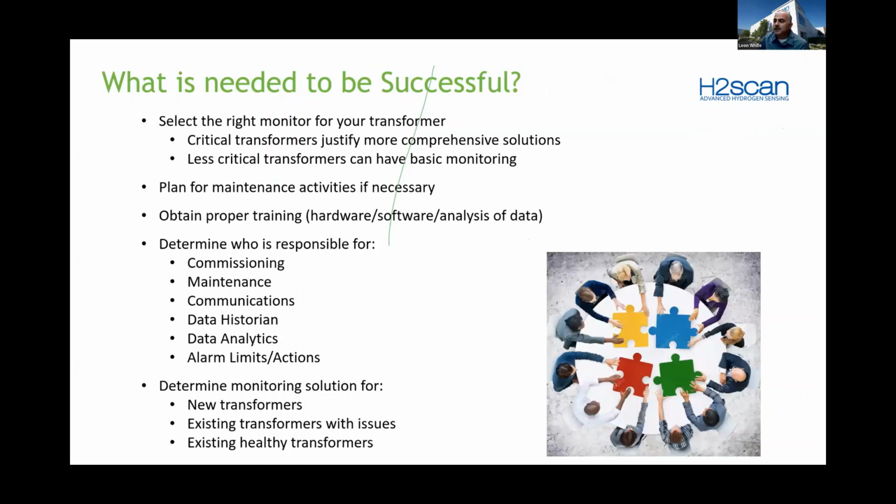So what do you need to do to be successful? First of all, select the right monitor for your transformer. Of course, critical transformers justify more comprehensive solutions. Typically generator step-up transformers are the number one thing I think of when I think of a critical transformer, because if you lose that transformer, you lose that generation, and no matter what the transformer costs, the cost of your lost generation is going to be significantly more.